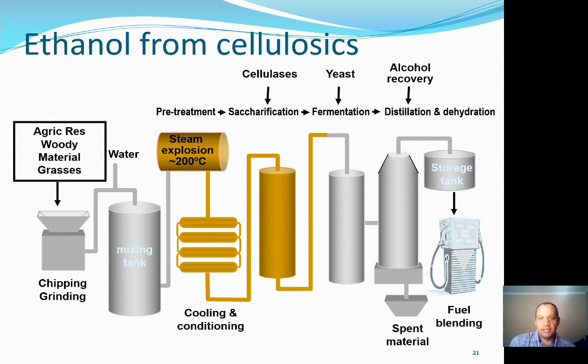your sugar polymers, mainly your cellulose here, because the pre-treatment methods quite often are very good at disrupting the hemicellulose already. So it's mainly the cellulose that still has to be saccharified here. And then you add your yeast, and we have a fermentation process similar to what you had for the first generation ethanol production. The difference here would be that your substrate loading is lower.